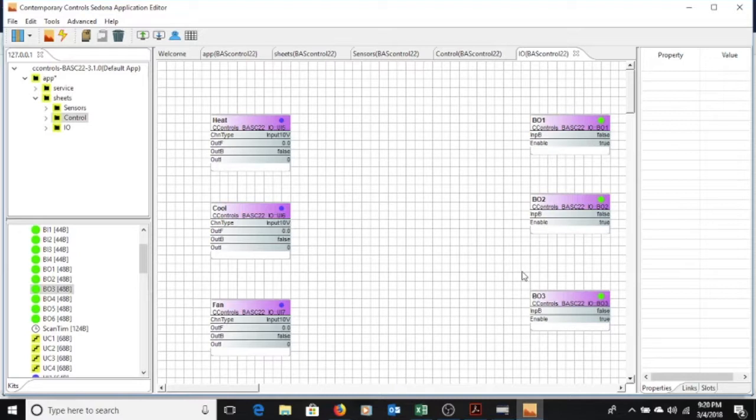These can also switch relays that can turn motor starters on and bigger contactors and other things that will help control your situation and isolate heavy duty power from the actual electronics and control. Remember, you always have to isolate your electronics and your control voltage from your power voltage. We do that in HVAC a lot with 24 volts and 480 or 240 volts in residential. But one of the things that we're not used to seeing is the electronics isolation.